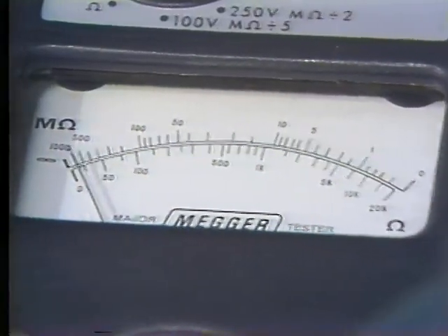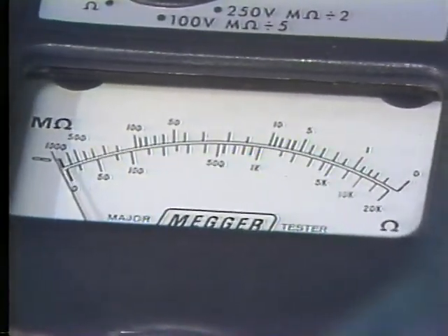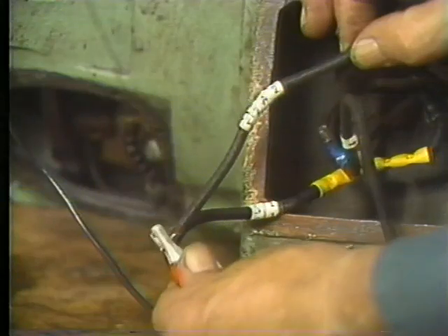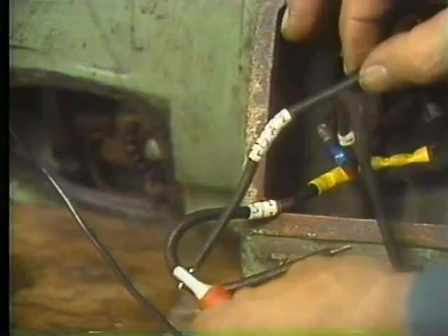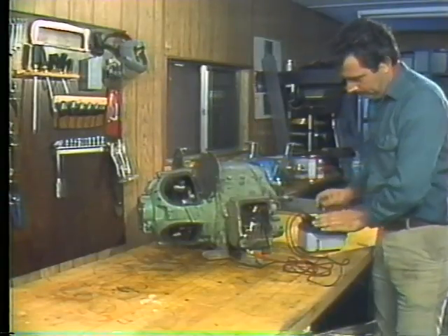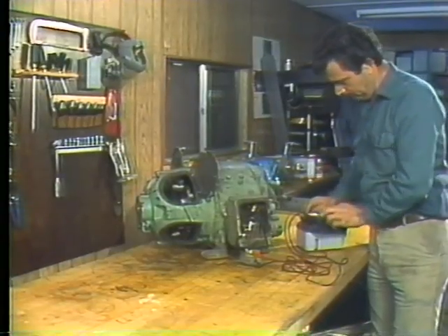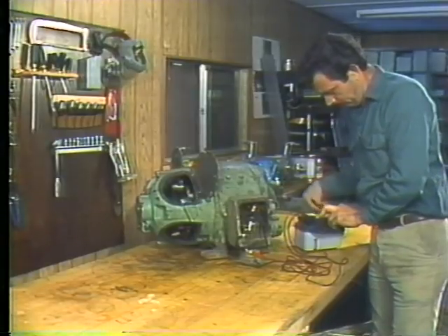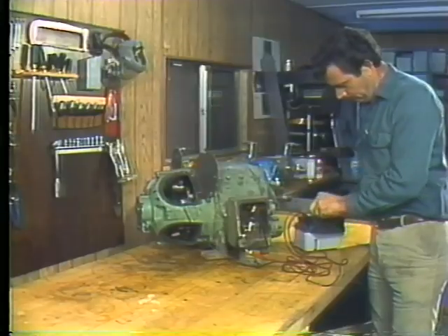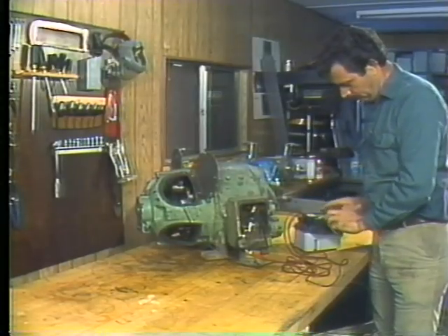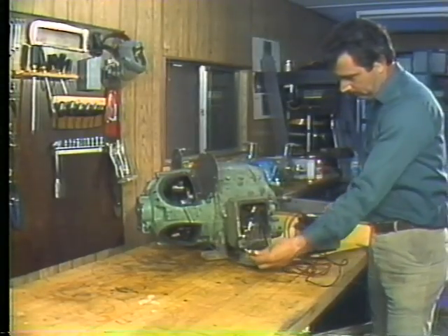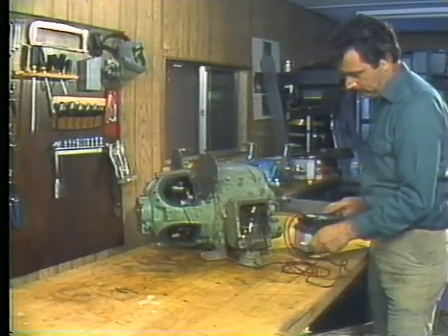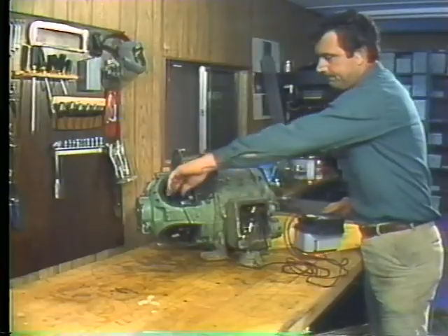Nope, the ground's not here. Let's go on to the shunt field. This time, the lead's marked F. Okay, here it is, and yes, it's grounded. But we're not finished. We've only found one ground. The armature might be grounded too, for all we know, and you've got to eliminate all possibilities before you begin the repair.